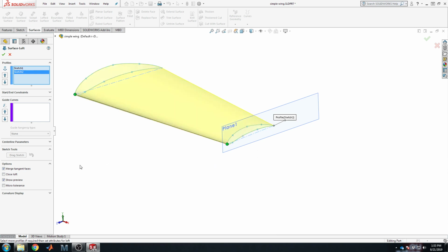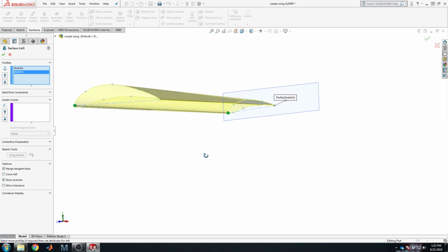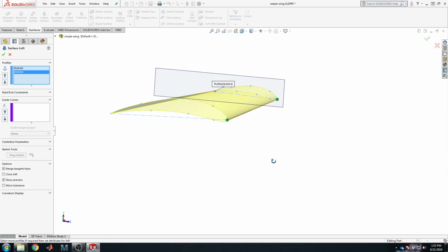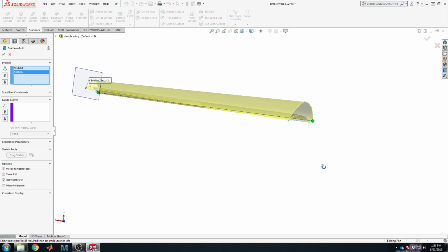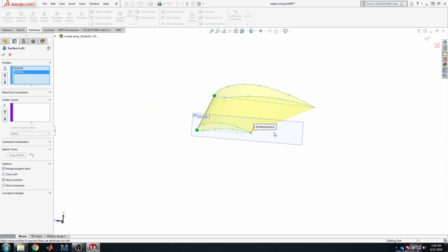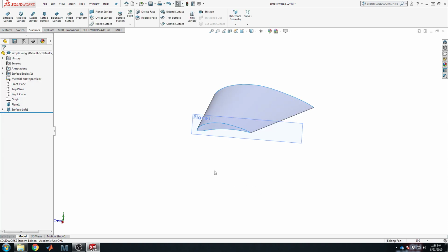Sometimes those control points are somewhat difficult, also known as extremely difficult, to move in SolidWorks, but keep at it, trying from different directions, and it'll work. So right now you see that this automatically did a linear interpolation in 3 dimensions between the 2 defined airfoils, so that you can go across your wing with any sort of washout, dihedral, sweep, whatever you want to apply to a wing, and it makes sure that the airfoil sections stay consistent in the geometric, streamwise sense. So for now, that's the simplest surfaced wing you can make.